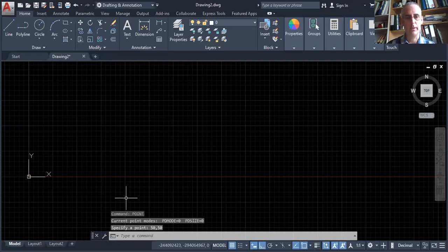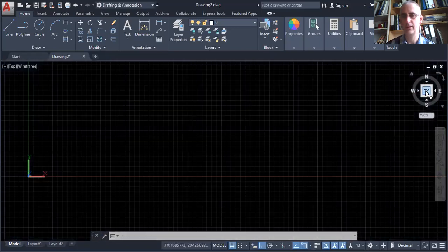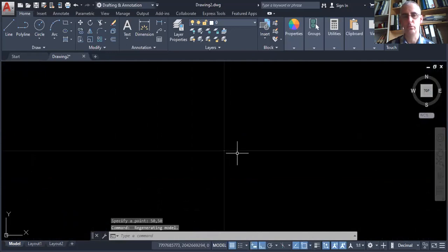And now you'll probably not see it straight away, but there is actually a point on your screen here. It's not going to come up straight away. So the way to do that is either to zoom in to what you've actually already drawn, or what I tend to do is I tend to go up to the view cube here and click on top, right? You've got to get right over that top and then click on that, and it'll zoom right into the point that you've drawn.